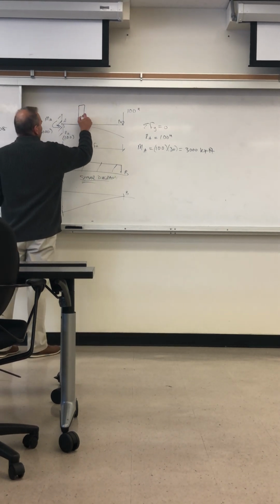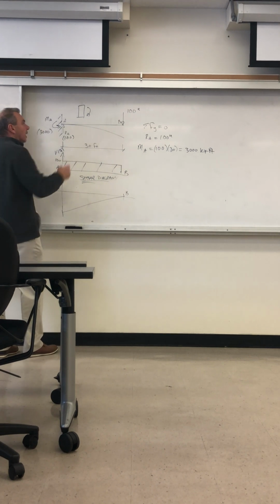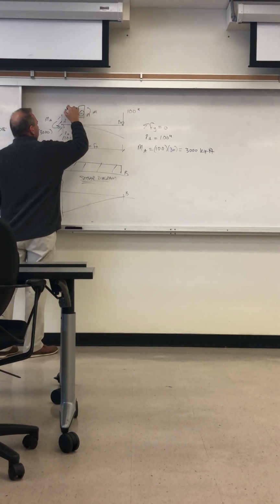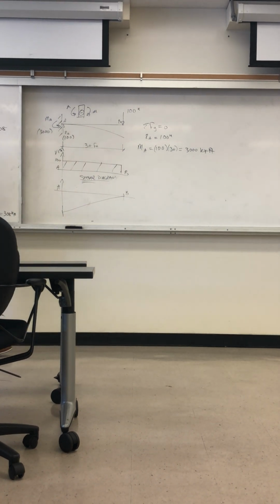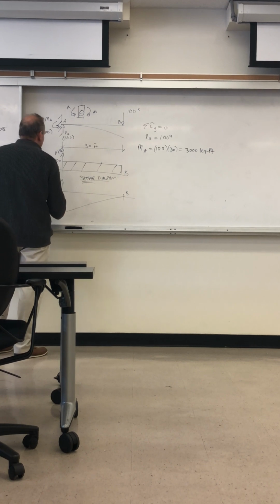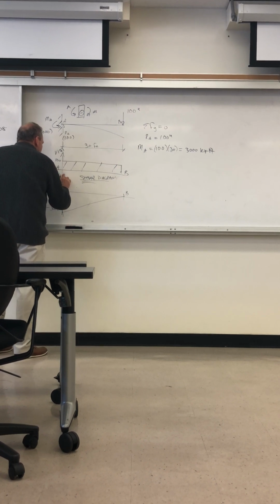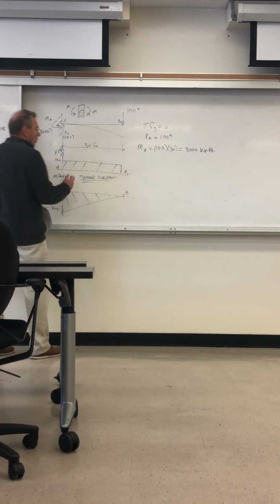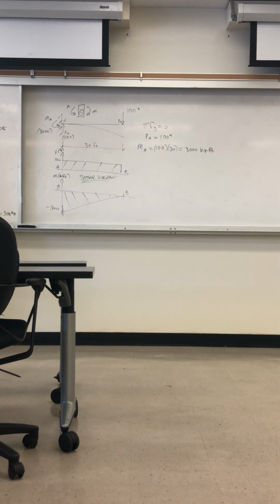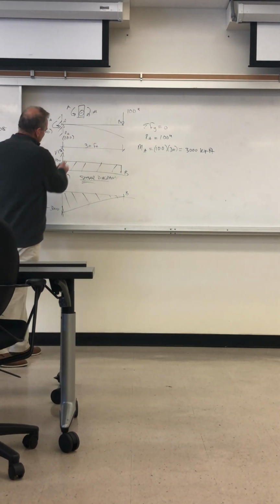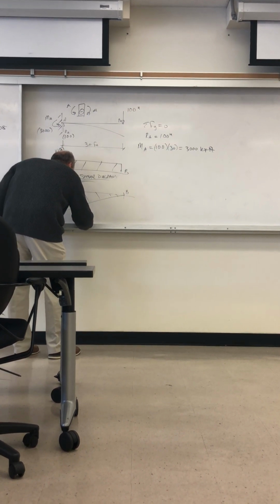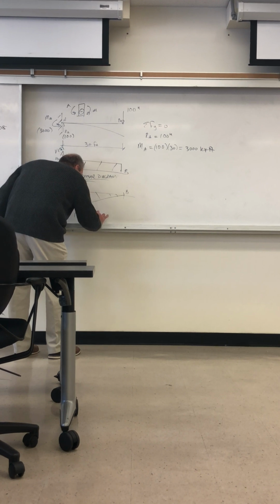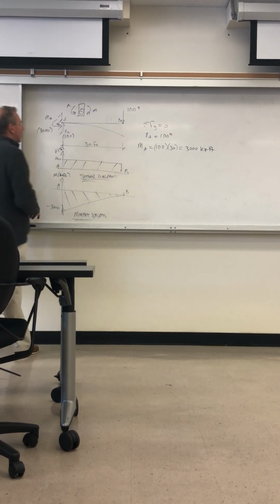If you take a slice here, you can see that force times that, some moment that way, and on the other side it's like that. So this is negative bending at all locations. It's opposite to our positive definition of moment. And so here this is minus 3,000. This is moment and Q. So it's plotted on the negative side, and that's our moment diagram. Notice how for most of these problems, I'm just calculating like 1 point. You don't have to always write equations. I didn't write a single equation for shear or moment diagram. I just drew it. Just calculated 1 point. This is 1 point. This is my moment diagram. And you can see the slopes and the areas, they all add up, so the shear and moments are interrelated with each other.